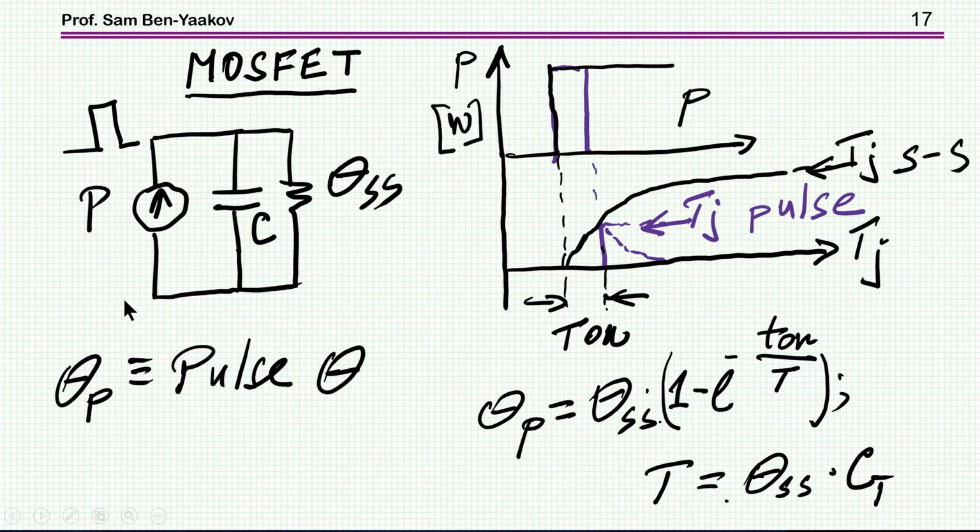Now, the transistor has also a heat capacity, so therefore, if you expose the transistor to a step power, that is, at a given point you start pumping in energy, it will rise. Well, depending on the model, depending on the structure, and as a first approximation, I'll assume it's a first order system. So the temperature will start rising, but if the pulse is short, okay, it's a short pulse, then obviously you'll get to a given point and that's it. And then, of course, the temperature will go down because the unit will be cooling down, okay?